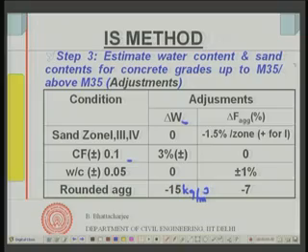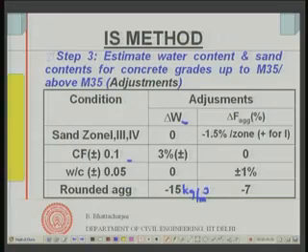So, what you can do is, the amount of sand that would be used can be reduced if you have finer sand. Finer sand means that for the same water content it would possibly need more water. Since I am not changing the water content, you should reduce the sand so that your water content remains the same and workability remains the same. It is also related to water cement ratio.